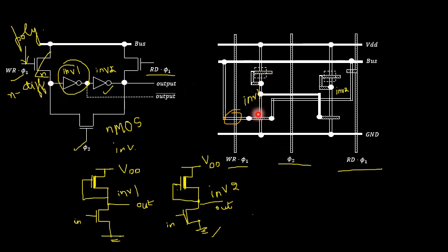So this is the inverter representation. Pull up will be the NMOS depletion type. So this is the depletion type of NMOS transistor. Pull down will be enhancement type. This entire vertical layer will be the diffusion layer, so that's what I have taken. The entire vertical layer is an N type of diffusion layer. So this is the inverter 1 stick diagram.